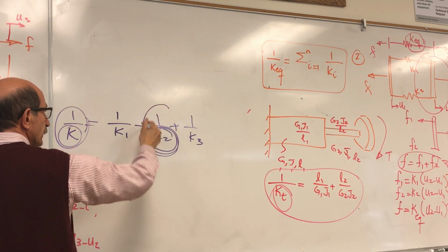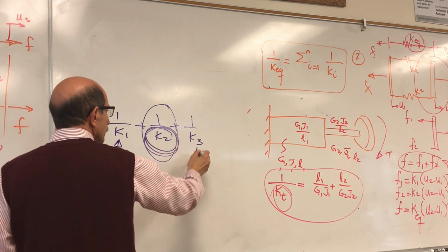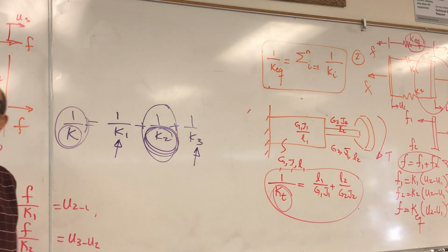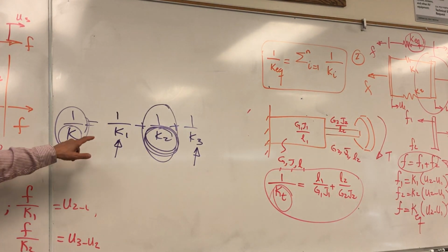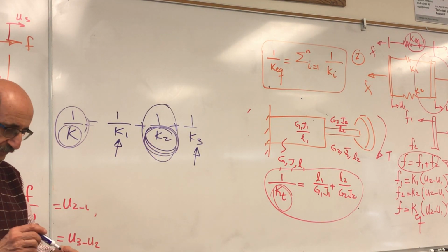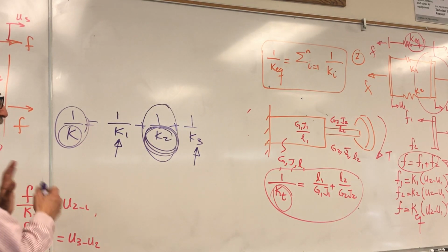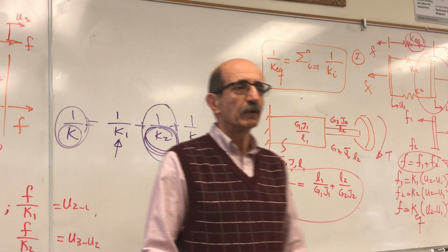That this term would be very large, right? So, doesn't matter. If you strengthen these, it is that weak spring that will dominate. So by strengthening the other stiffnesses, it doesn't matter if you have a weak link and you don't recognize that these are all in series, just by strengthening the others, you're not doing much.